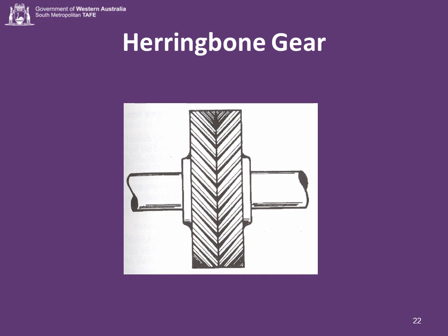The gear teeth of both hands cause the thrust of one set to cancel out the thrust of the other. Thus the advantage of helical gears is obtained, and quiet, smooth operation at higher speeds is possible. Obviously they can be used for transmitting power between parallel shafts. They're commonly called double helical because they have teeth cut with right and left hand helix angles.